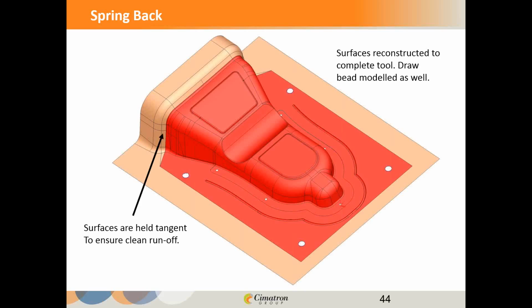When I showed you the draw bead earlier in running the blank function, we asked for the center line and we asked for a pressure. So really it's kind of a predictive tool for a draw bead. Wherever I go, it seems every shop has their standards for draw beads, how much distance away from the part, how much clearance they want, how big they want it. So it's not like you're constricted to using any specific type of draw bead. You can make it the way you want.